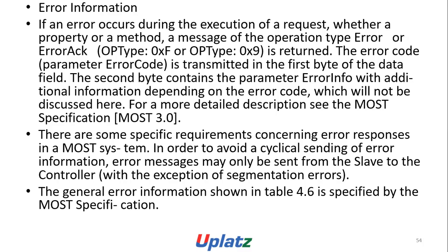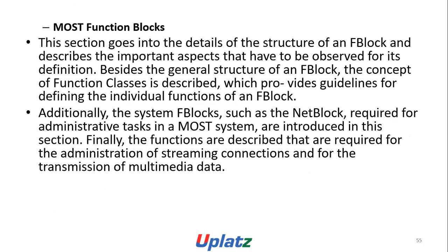There are some specific requirements concerning error responses in the MOST system. In order to avoid a cyclical sending of the error information, error messages may only be sent from the slave to the controller, with the exception of the segmentation error. The general error information shown in table 4.6 is specified by the MOST specification.